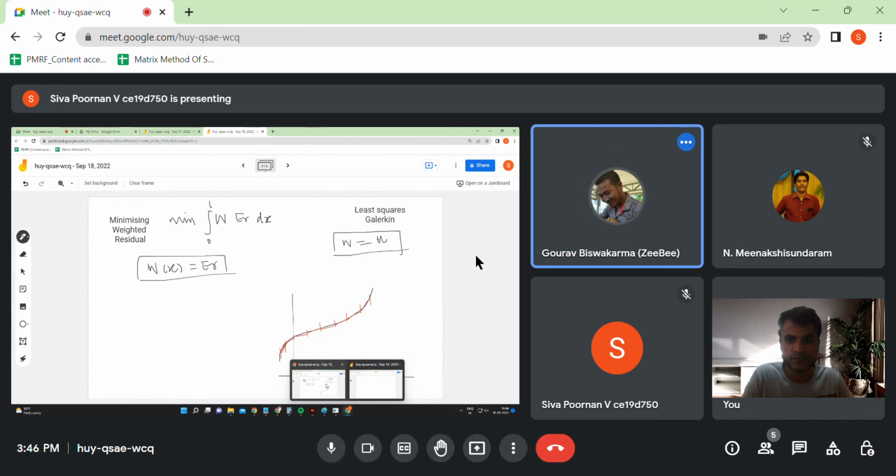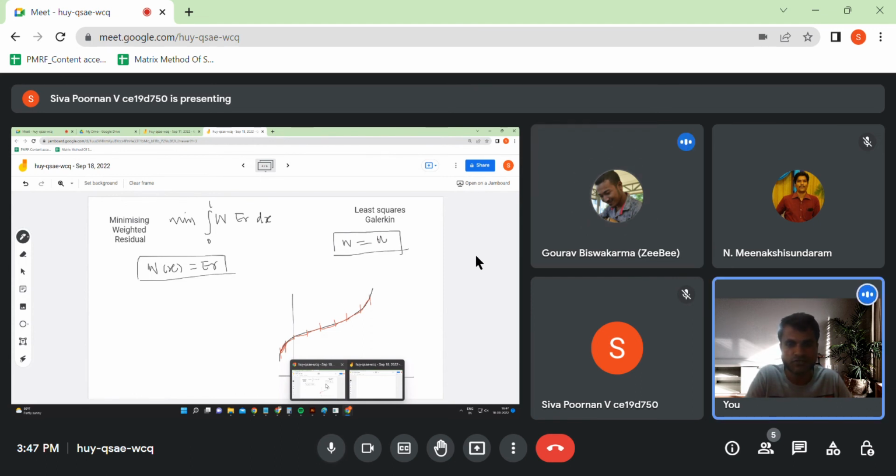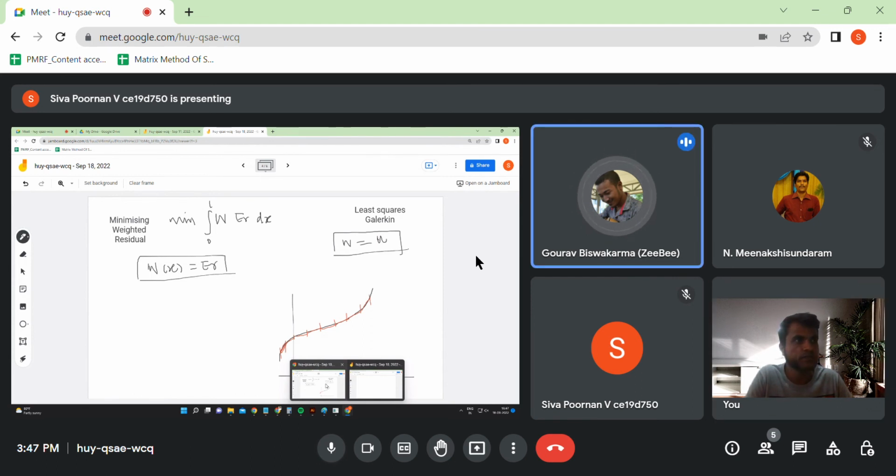Okay. One part of the course was the assumptions that were explained for deriving the shape functions of the beam element. Those assumptions I want to clear up because in the course maybe I couldn't understand them better. Can you state the assumption on which you are having confusion? Assumption one was the Euler-Bernoulli assumption that plane sections remain plane, that is okay. Fine. Another one was that we are taking the deflection for the top fiber, bottom fiber, and mid fiber the same.